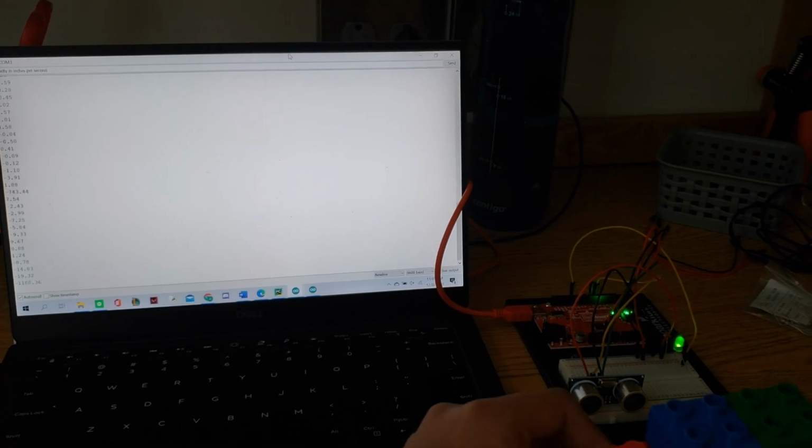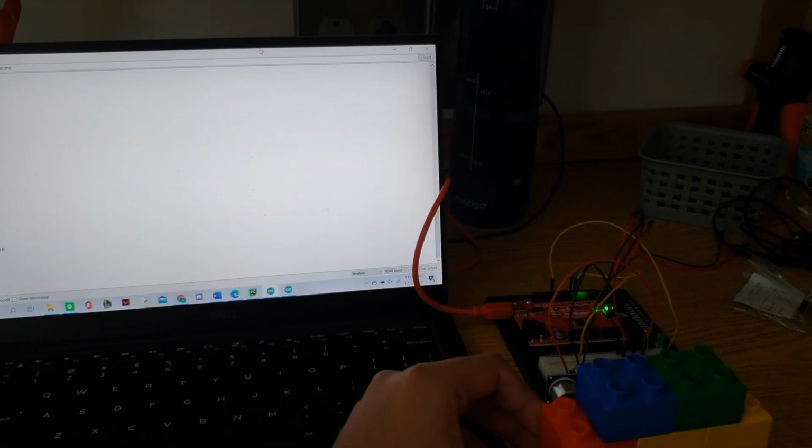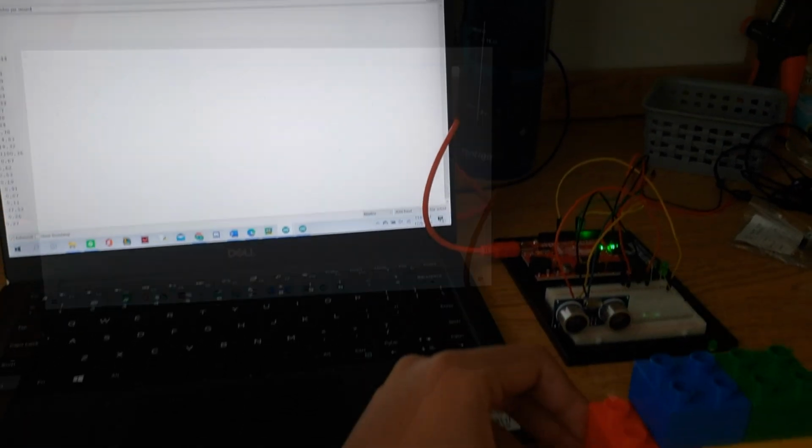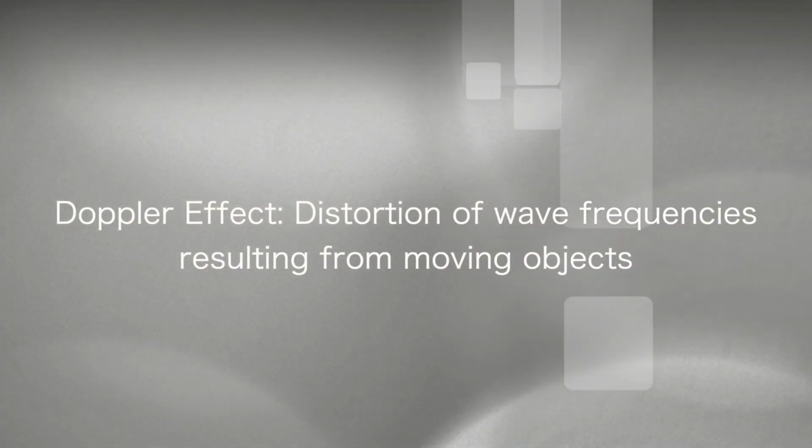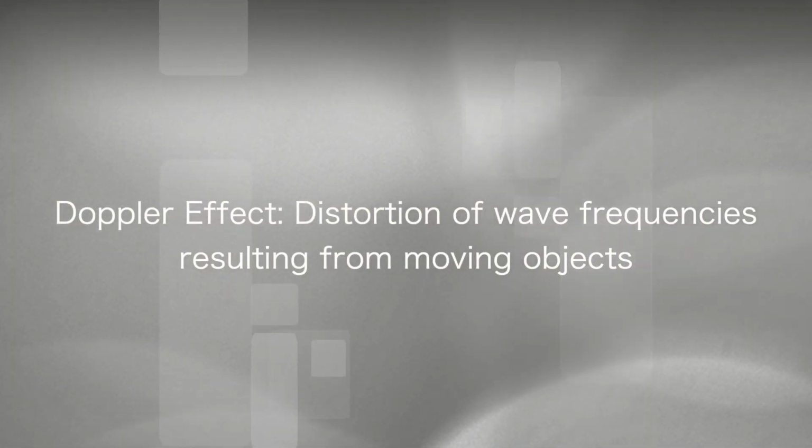By continually tracking this time delay, a few basic calculations can be made to actually track the velocity of the object. Another common way ultrasonic motion detectors work is by taking advantage of the well-known Doppler effect by comparing the frequency of the transmitted waves to the returned waves.